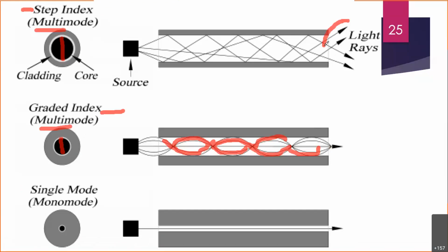So you see over here, pulses are coming out at different times, the arrival time is different, and because of that the signal is getting spread. But here you see all the signals, whatever path the light signal follows, will come out at the same time. So that is why here you will get a high intensity peak compared to this side, because here the individual pulse strength is almost the same as the original one, but collectively this is going to be spread like this, while here it will be very clear like this.